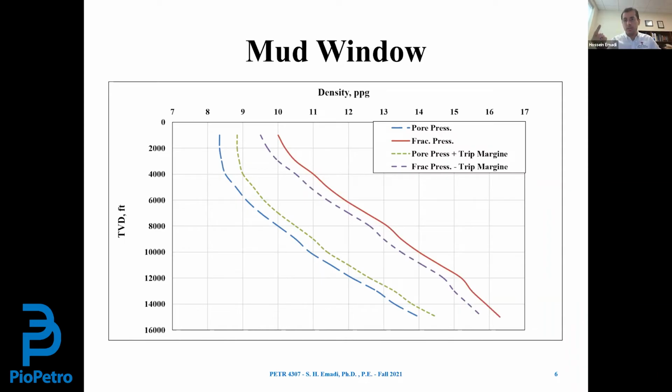And we know that when it starts moving upward, we always have friction acting in the opposite direction of the flow. Is that correct? So when the drilling fluid is moving upward, friction, or pressure drop due to friction, is acting downward. So bottom pressure will be that amount of pressure, which is equal to the pressure drop due to friction plus the hydrostatic pressure of the mud column inside the annulus.